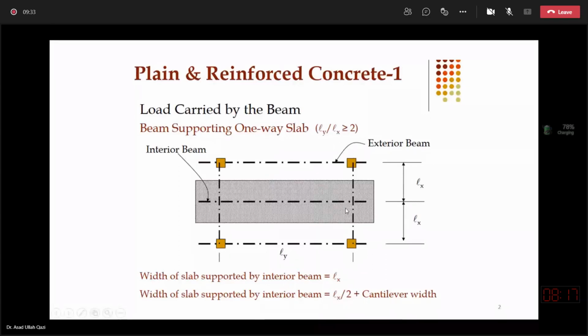So it seems that there are two panels now which are resting on these beams on the perimeter, and if we measure the dimension center to center of the beam which are running on column center lines, or this secondary beam which is present, which is dividing the center to center distance of column exactly into two sub panels, that dimension is then L with subscript X. So this is actually the dimension center to center of the two parallel beams, and it is the shorter dimension of this one panel, and the longer dimension of this panel is L with subscript Y.